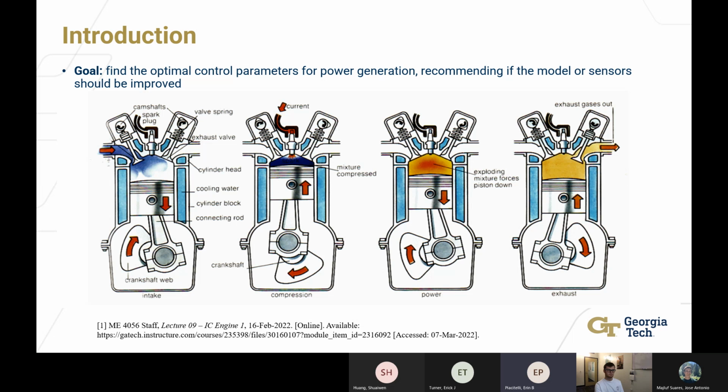Generative Energy Systems Incorporated has developed a unique generator based on an internal combustion engine that can be powered by either compressed air or propane. A 48-volt BLDC regenerative motor is attached to the engine to start the engine and generate electricity to be stored in battery packs. This experiment is focused on finding the optimal control parameters for power generation. This is achieved by characterizing both the mechanical properties and fluid exchange properties of the engine.